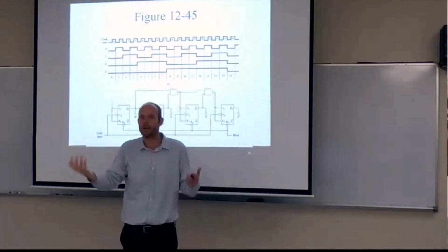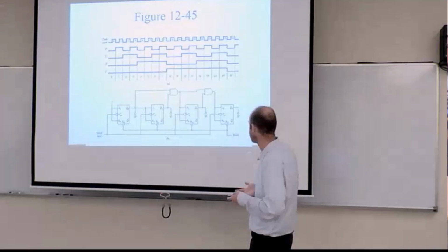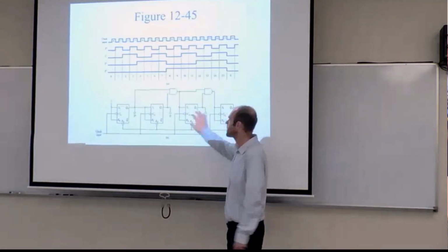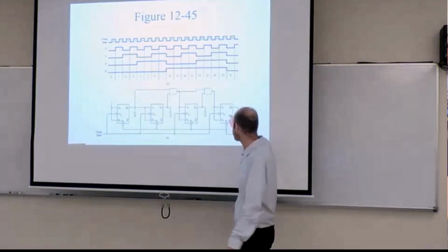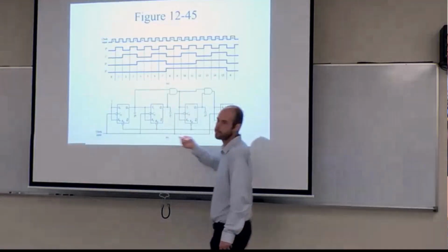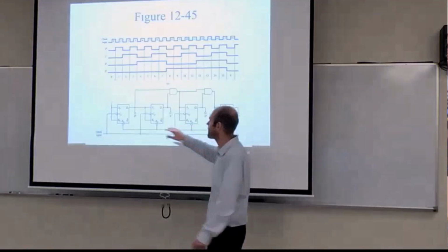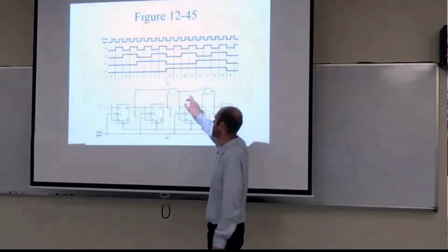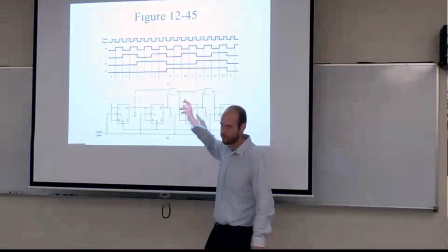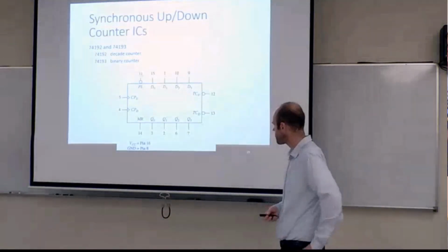So we're just setting up the logical situation so that the timing counts accurately. But fundamentally, for a synchronous counter, every device is clocked by the same clock input line here. So you are able to go faster, not limited by the bit number, but limited by really the propagation delay of your logic. So you have a much higher speed possibility.